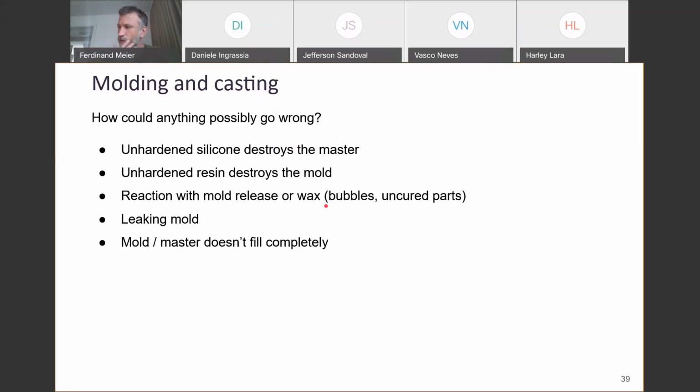So a common thing is you put a little bit of plasticine just for separating one part from the other. Funnily, plasticine reacts very weirdly with silicone, so it just stops curing. So whichever material you're going to use, if it's hot glue or wax or plasticine, make sure that there's no funny reactions with your casting part.